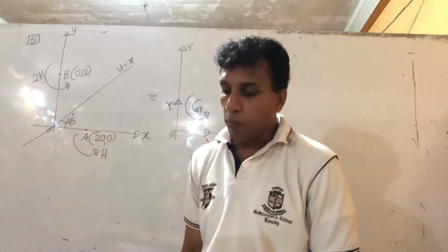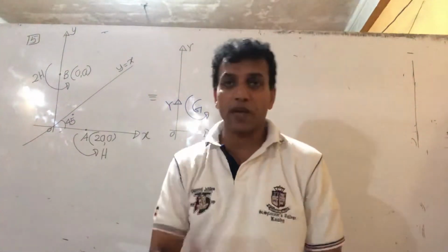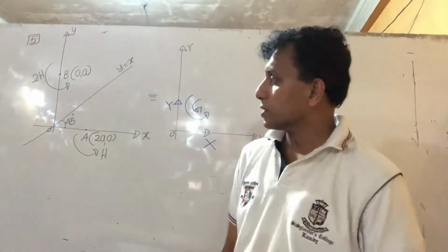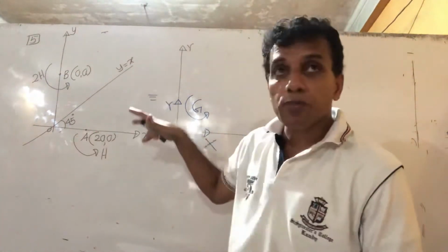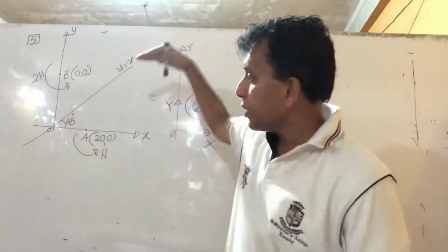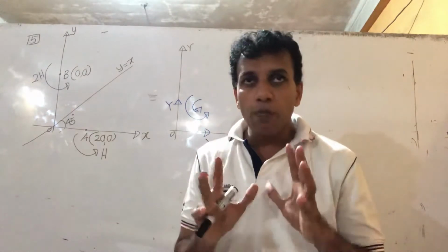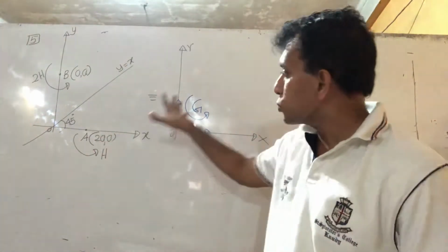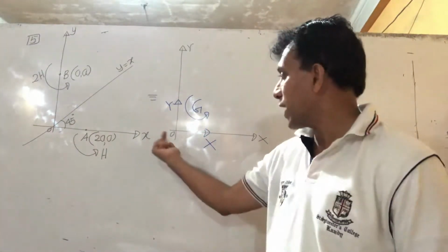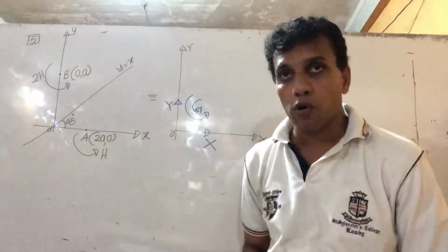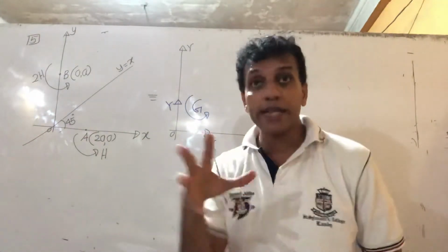If the resolving component is parallel to the line y equal x, you know y equal mx, the gradient is 1. Y equal x passes through the origin, therefore 45 degrees here because m is 1, right? So the forces resolved parallel to this line, that component they say is 0. Every coplanar system can be reduced to this pattern: a single resultant force at the origin, with total x component and total y component, and it can resolve to a moment or a couple at the center.